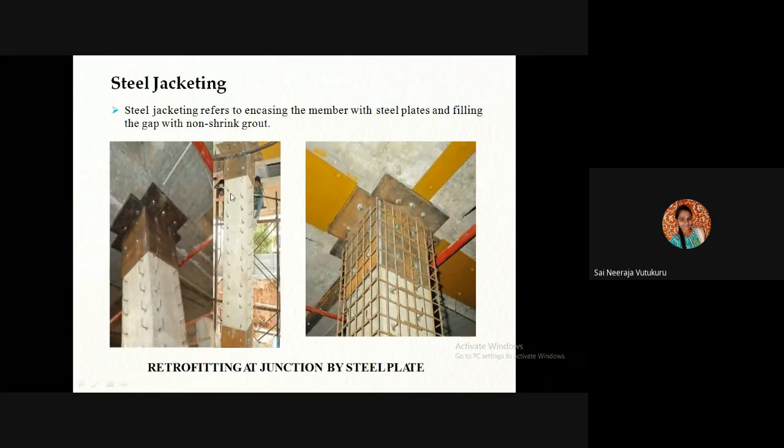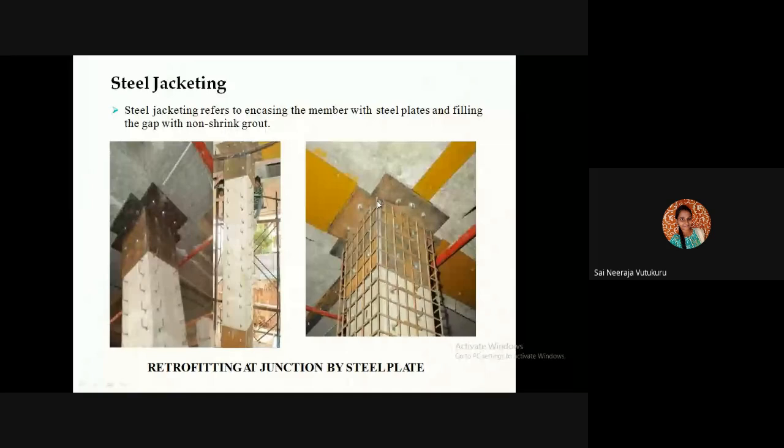After that, we select the existing columns which are less in strength. We take the dimensions of the column, cut the steel panels, and place them onto it. Whatever steel panels are placed here will be further connected with steel reinforcement also, if needed. It depends upon the conditions whether we require further steel panels or whether reinforcement is also required.